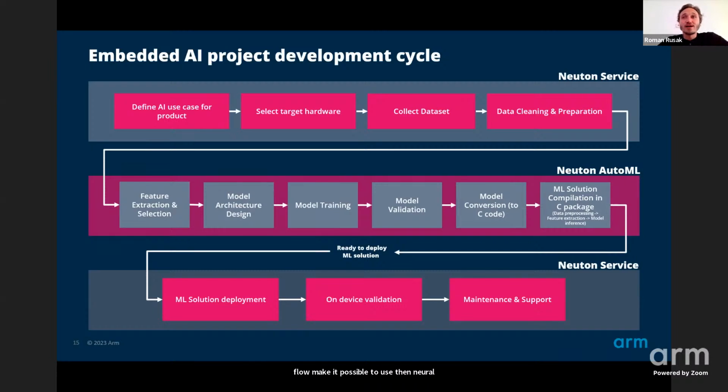But with feature extraction and data pre-processing, everything is not so simple. When you work with your Python code, you can use libraries and extract hundreds of features, use different filters, overlapping windows, etc. in just one click. But then you have to repeat all of this in C code, and this is not so easy. But doing it efficiently is even more difficult. So keep that in mind.